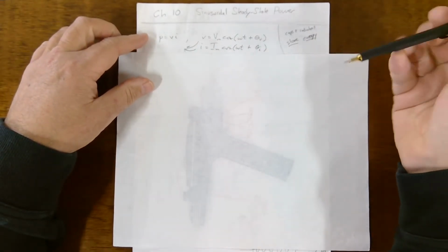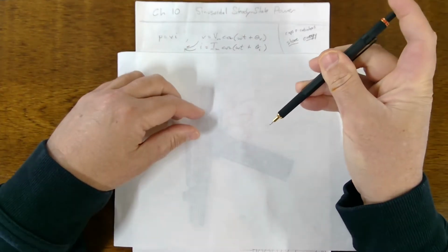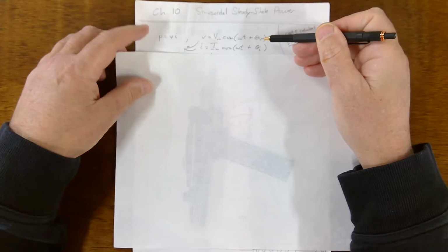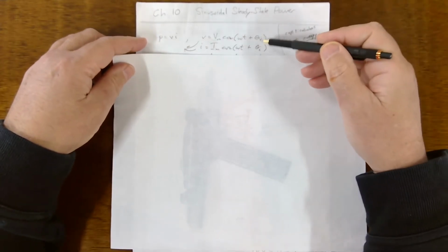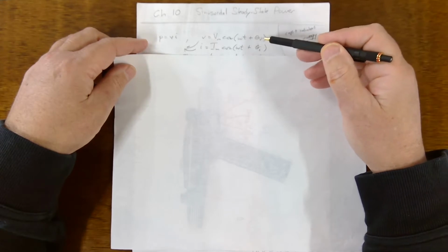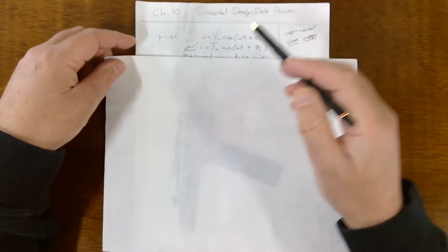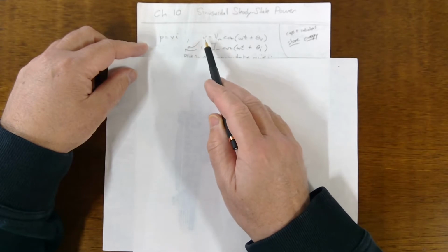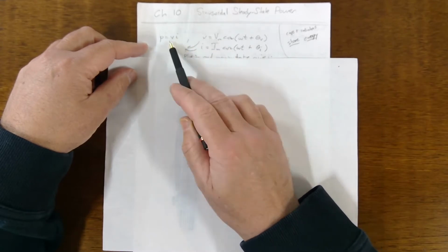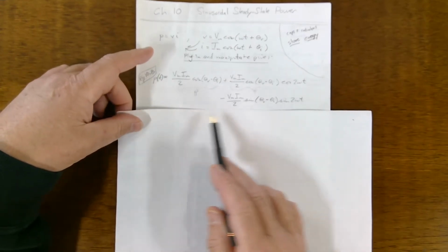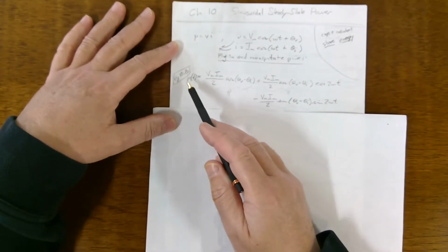Often for convenience, if we're not given a particular phase shift, we'll set one of these to 0, typically the voltage. Okay? So if we're not given both of these phase shifts, then it's convenient to set one of them to 0. But anyhow, P equals VI, and V is this and I is this. So if you just take these two equations for V and I and plug them into VI and then do some algebra, you're going to get this big guy here. This is equation 10.8 from the text.